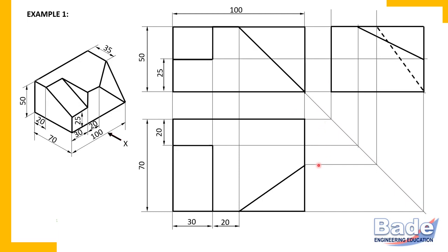So here 30 millimeters, instead of inserting 30 millimeters here, you inserted here 35 millimeters. In absence of side view, we would have inserted 35 millimeters here. Okay, so this is how I have inserted all dimensions. Remember, you must insert dimensions, and you should insert dimensions after completing the drawing. And then, since we are using first angle method of projection, use that symbol of first angle method of projection. So this is how we have completed the drawing.